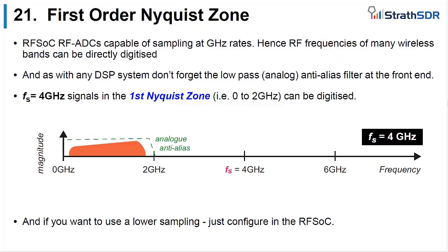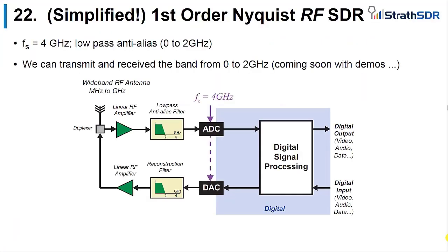We filter everything that's above. So we'll pick out this band here, and anything above, nope, that's gone. We don't want it. And if we do that, then we will find that everything's good. And there's a single input, single output system. So we can take it to our FPGA and do our DSP or our software-defined radio, however we wish to refer to that.